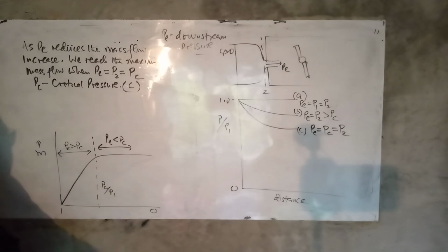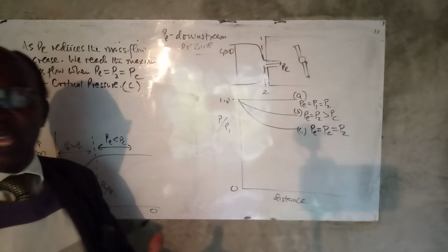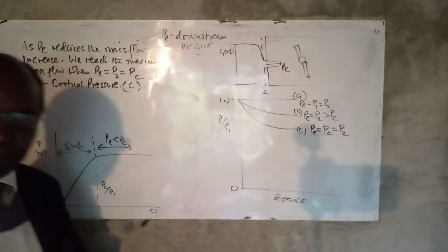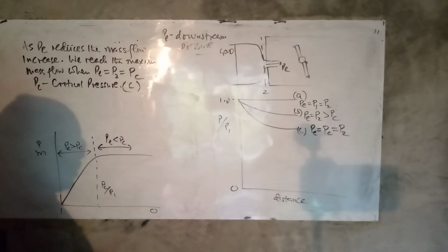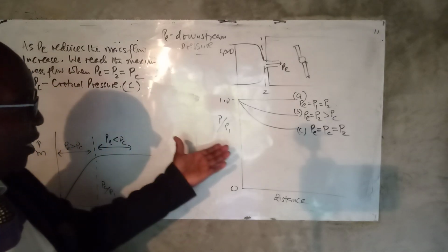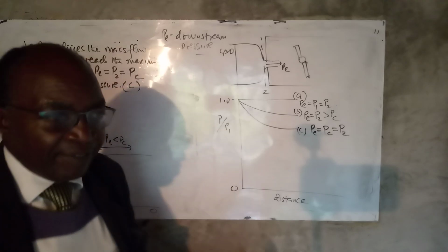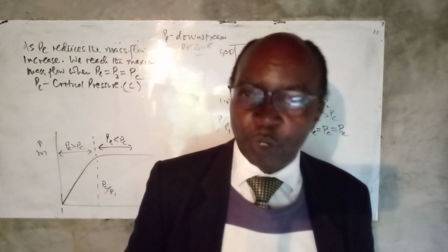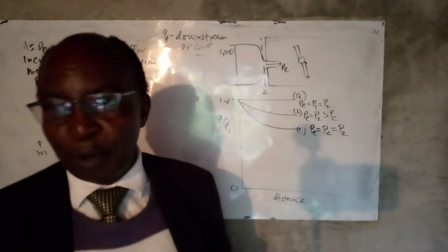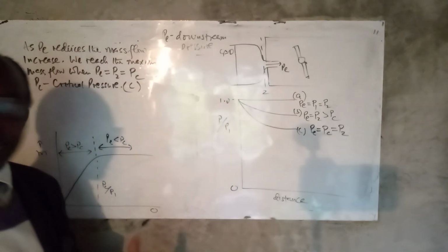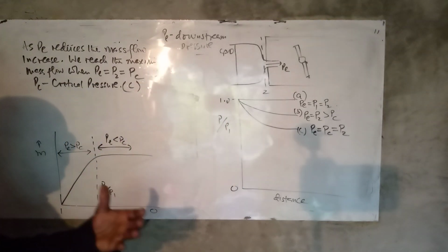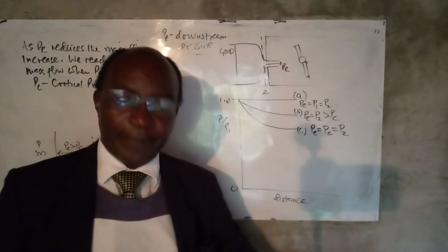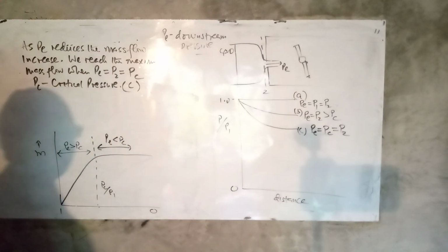Now, we don't want to reduce PE further, because it cannot be less than that critical pressure ratio, unless, for example, we have another throat upstream of that plane 2. Then probably we will be in that kind of situation.